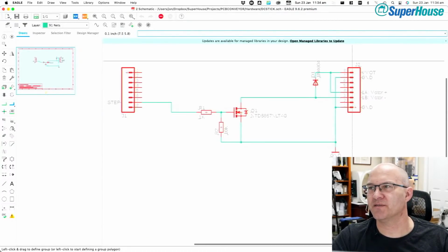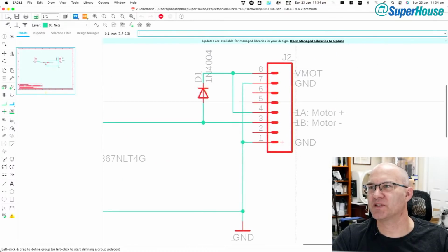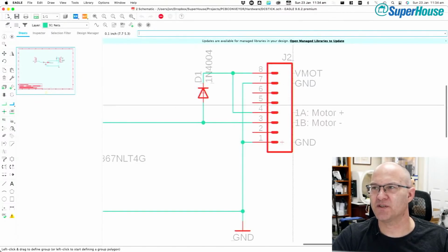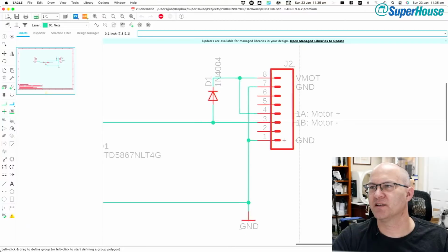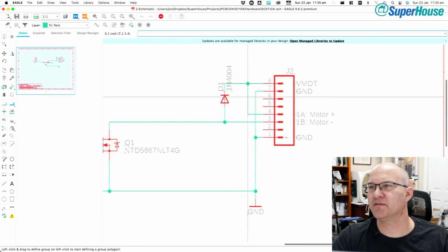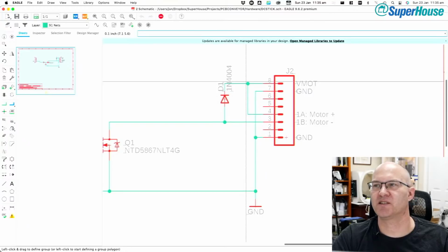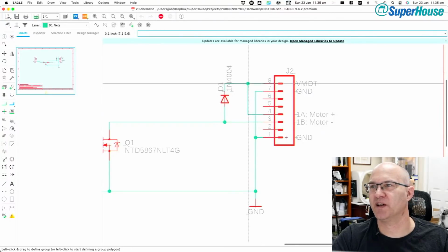So these are the connectors for that little stepper motor footprint. We've got the voltage coming in for the motor, we've got a ground connection, and then normally you have 4 wire outputs coming here. There would be 2B, 2A, 1A, 1B are the 4 outputs here. So the 2s are just missing, they're not connected to anything. And then the 1A and 1B connections go out. So we've got positive, you can't even do direction control with this. It's just controlling an output with a big fat MOSFET.